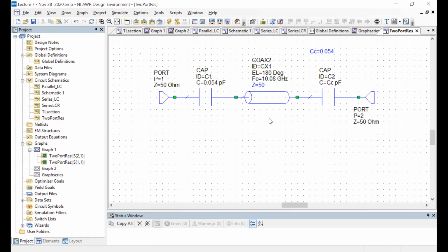In the case of the qubit, it's the quantum state of the qubit which causes the resonant frequency of this section to change, and one uses that to infer the state of the quantum system. But more generically, in many different kinds of physics experiments, one couples a quantity of interest, which you're interested in detecting, to the resonant frequency of some circuit or device. By looking at changes in resonant frequency, you can infer the change in the actual quantity.